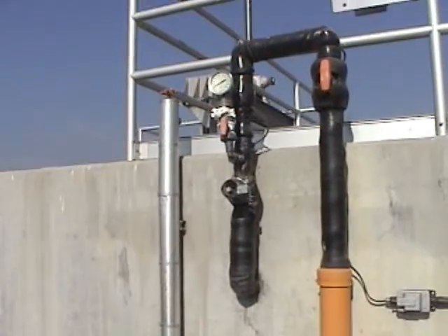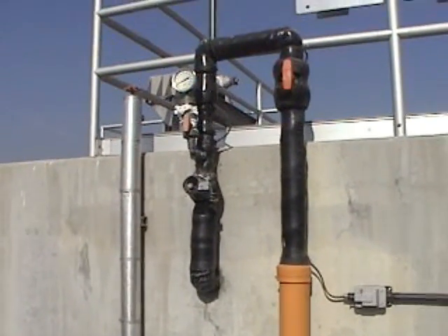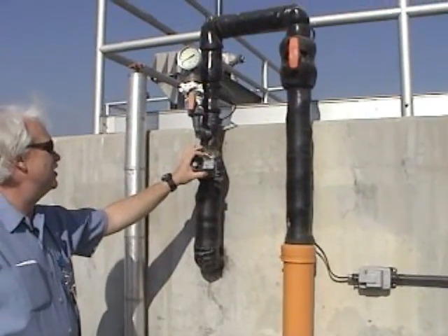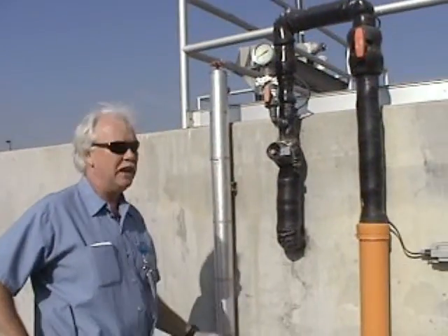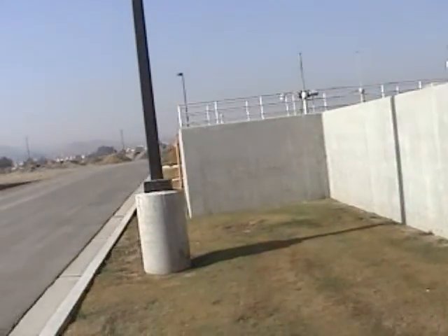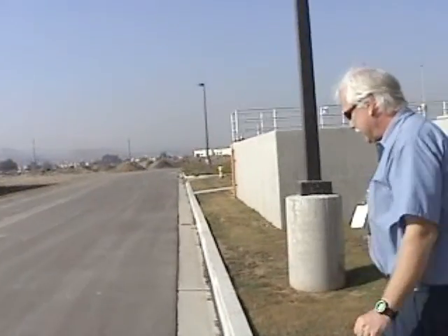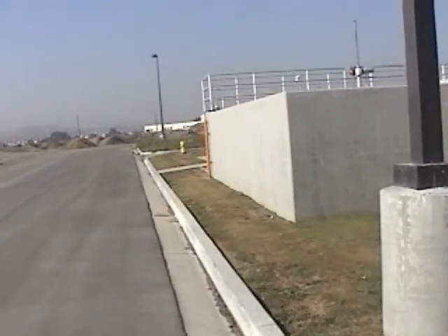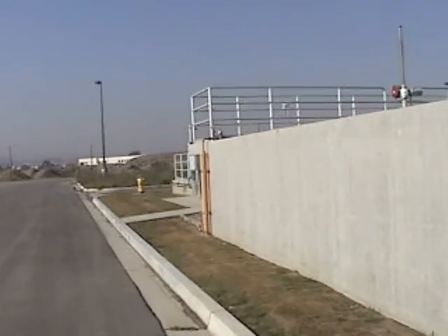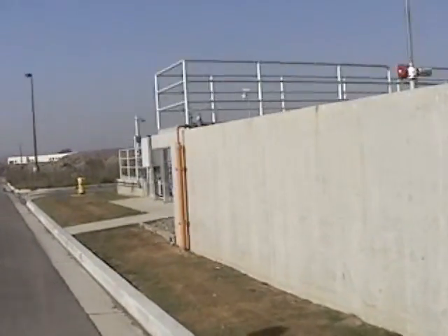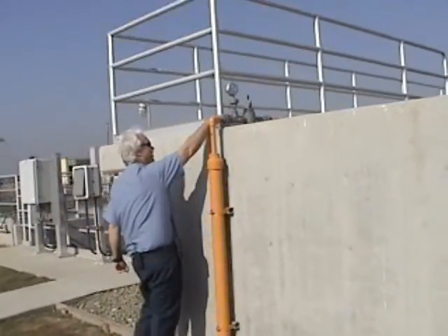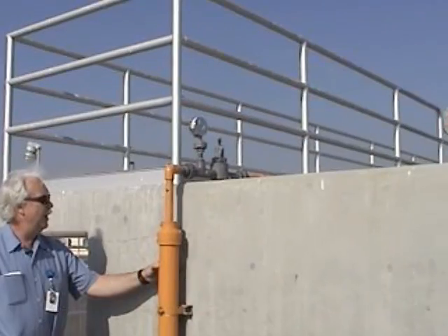This is really important: we're dechlorinating from this, so to service this back pressure device or work on this pipeline at all, you would have to dechlorinate the plant's effluent from this other line over here. And this line here is connected directly to pump number 2. So you would have to dechlorinate using pump number 2 through this pipeline over here. And you can see this has a back pressure device on it also. It's not heat taped.